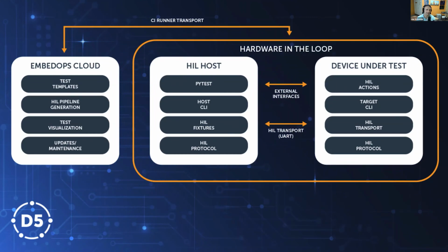What I've consistently seen teams naturally gravitate towards is a Python executor running on a HIL host, usually talking over some sort of serial port for the majority of the tests. Sometimes you have custom GPIO, and there are Python modules that will talk to National Instruments equipment or general GPIO. That's where people naturally gravitate, and that's why our test templates are all based on PyTest and a Python environment.